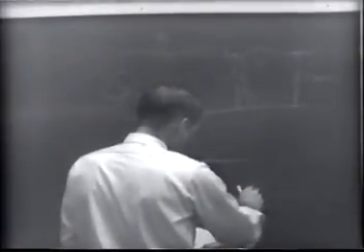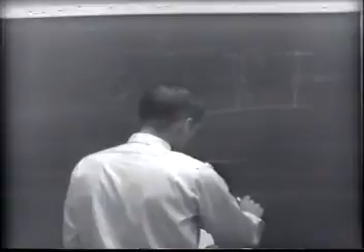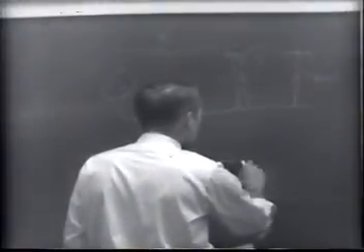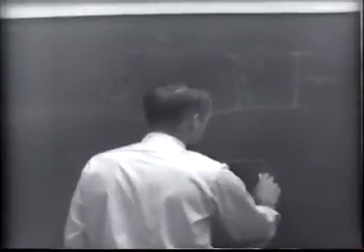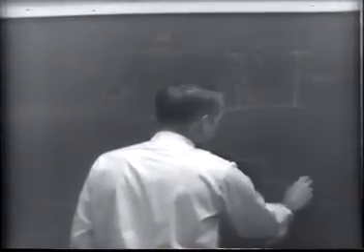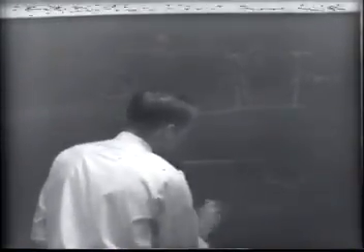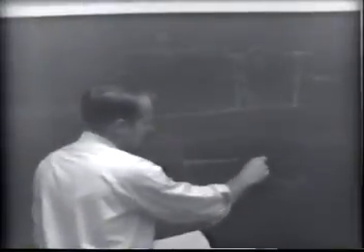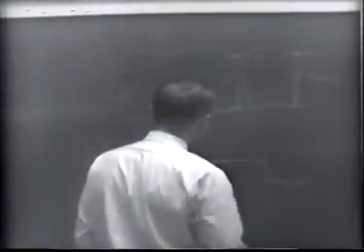And at that time, at the next current zero, at this point the fault would be cleared because the current would be going through a zero crossing right there.